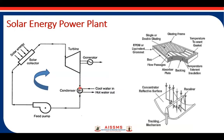To convert it again into water, we have to use the condenser. Here the cool water will be circulated inside the condenser so that the temperature of the mixture will decrease and it will be converted into water. Again, with the help of the feed pump, we can circulate the water through the collector where it will be converted into steam. Then steam will be directed onto the turbine blades, and so on. The cycle will be continued. So this one is the solar power plant.